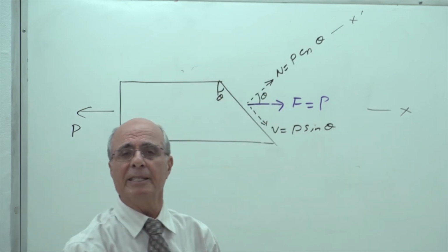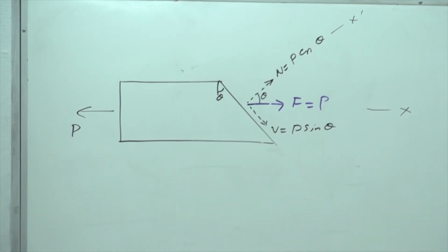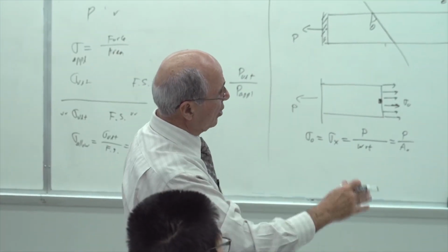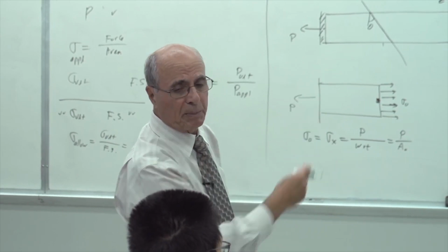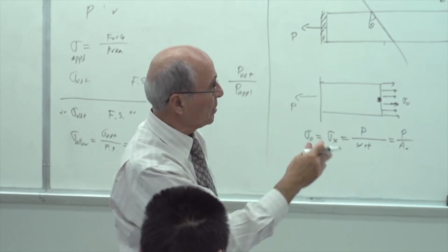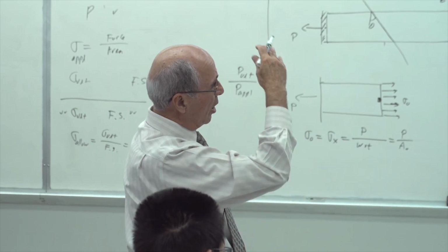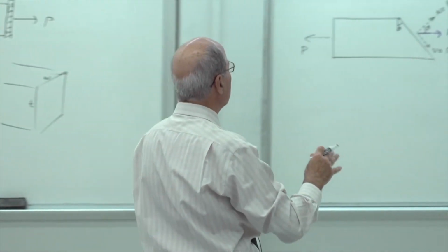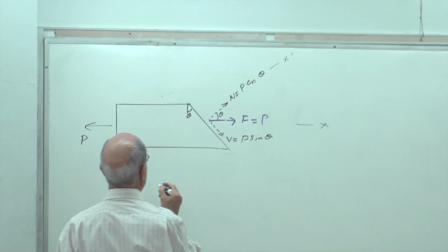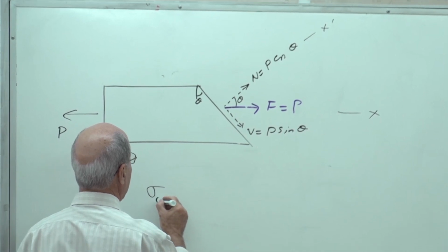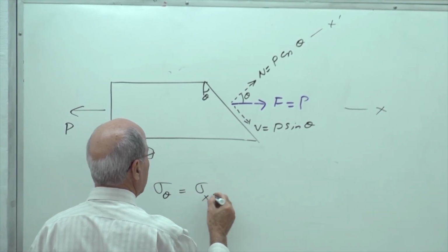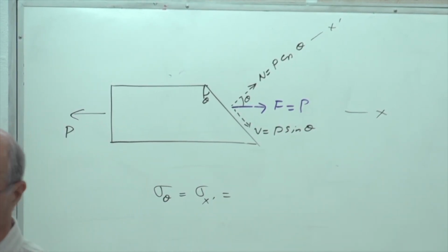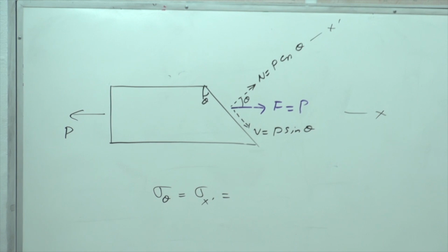Suddenly we are rotating it by theta degrees. Theta degrees could be 30 degrees, 40 degrees, and one of the axes is along that slope line and one is perpendicular. Is that correct or not? X prime is perpendicular to that inclined surface and y prime is along that surface. Is that correct or not? For future reference in chapter 7, here they call it normal stress, which they call it like that. First they call it sigma theta. I would rather you call it sigma x prime, which is in the direction of x prime. Is that correct? This is again for future reference, not for this chapter.